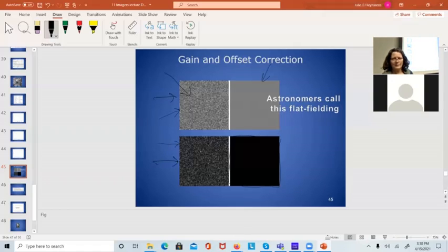The problem was that I just stopped it after about 2 or 3 days, after we got the data. We didn't spend a long time on this. I started looking at this, and it just hit me, I knew it was wrong: this dark current is a function of temperature. It's one of those strongly exponential functions of temperature. So your PUF changes completely if the temperature changes. So that was not a good PUF.